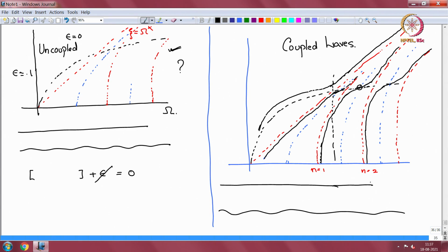as they are coupled, if I put a pressure sensor in the fluid or I put an accelerometer on the plate somewhere at a certain frequency, at a certain non-dimensional frequency, if I take a vertical cut, okay, I will see this wave, this dark black line and this dark black line. I will see these two waves, or these two waves are possible. Okay. The dispersion equation gives possibility of waves.